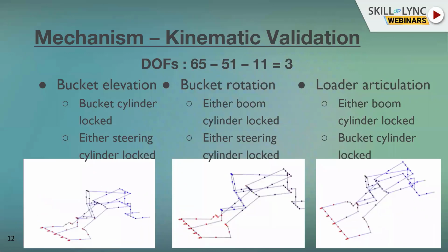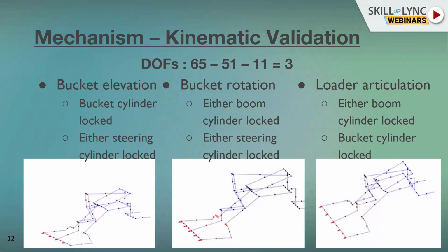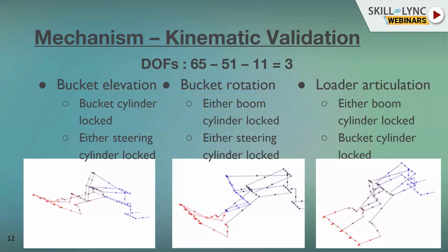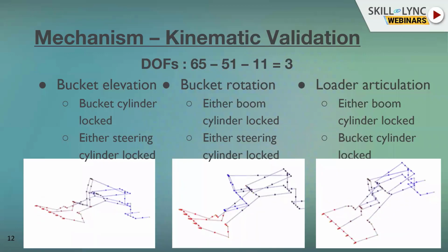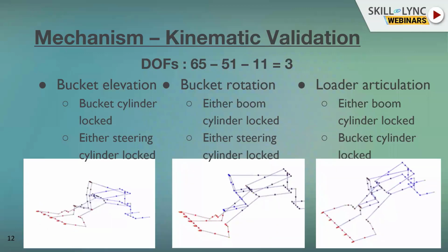Now this is an important exercise because most of the time, especially in industry, you simply use the tool to blindly model your mechanism, and people start applying constraints just to run the simulation. So they don't develop that insight as to what degrees of freedom have to be captured and how they are going to be captured, or maybe they over constrain the model. Over constraining the model means that we are applying more internal constraints than what is needed, and because of that your system basically becomes statically indeterminate. So you have more variables than the equations from rigid body mechanics, and you cannot get a unique value for the forces of all those unknown variables. So it is very, very important that your mechanism is optimally constrained and you are capturing the correct degrees of freedom.